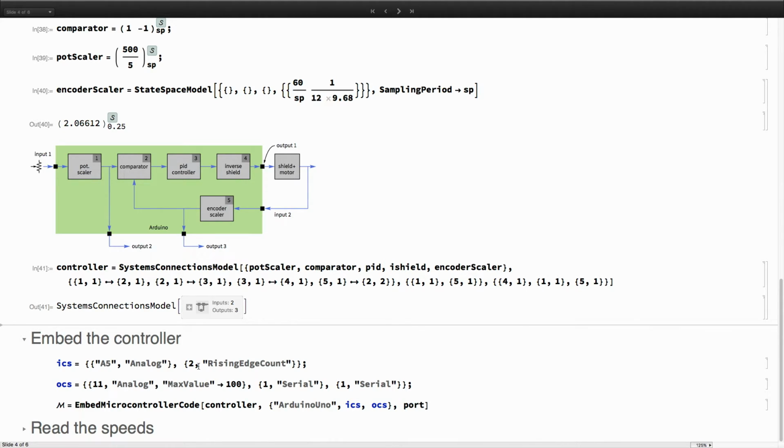Now there are several ways you can count the pulses. You can count either the rising edges of the pulses, or you can count the falling edges of a pulse, or you can also count the number of toggles the pulse is making. If I change this to the number of toggles, I'll have to double this, make it 24, but I just chose to go with the rising edge, so I'm just counting the rising edges, so that will give me the number of pulses.